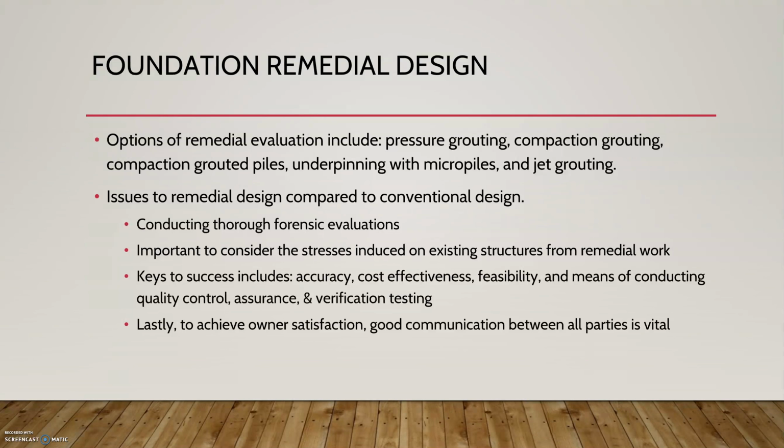The options of remedial evaluation included the pressure grouting, compaction grouting, underpinning the micropiles, as well as jet grouting. There were some issues with this remedial design. You had to conduct a thorough forensic evaluation, and some keys to success would include the accuracy, cost effectiveness, feasibility, the quality control, and assurance.